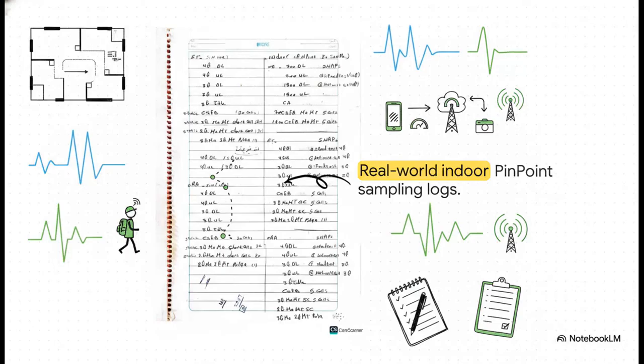And honestly, looking at this logbook reveals just how meticulous this entire process is. This specific entry we're looking at shows an indoor pinpoint test. The field engineer literally has to walk to 30 specific physical locations inside a single building, and at every single pinpoint, they execute a whole series of stress tests. We're talking logging 20 static CSFB calls, running network speed tests, and taking snapshots of the RF environment to figure out exactly where and why the signal dies inside that specific structure. Talk about a giant puzzle.